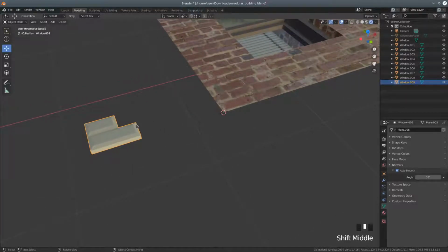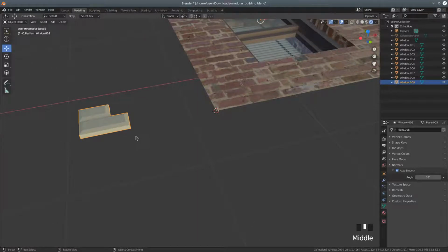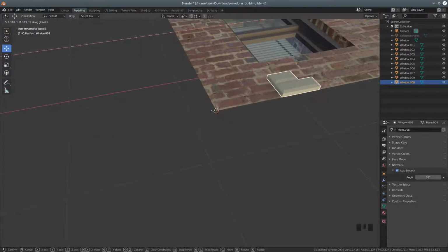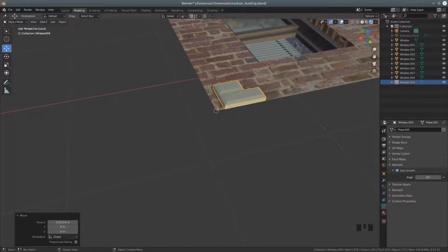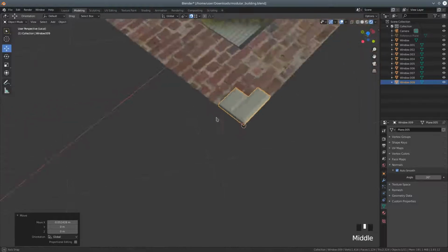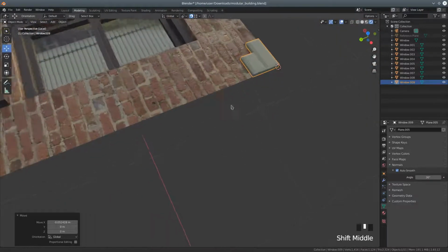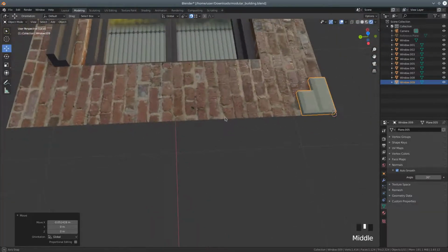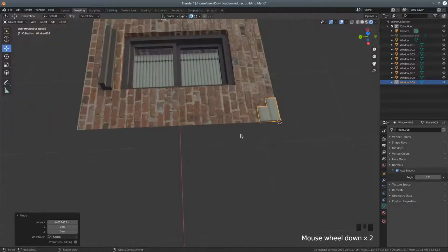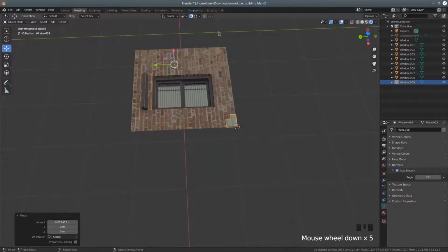So I'm going to press G to move, and then X to make sure it moves in the X direction. So let's have a go at that. G and then X, and we can move it across here, and hopefully if we make sure our snap is turned on, G and X, let's see if we can snap it to this corner. Yep, there we go. So now I'm going to duplicate that, but on what would be the Y direction, the green direction.